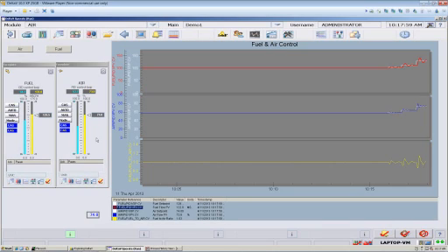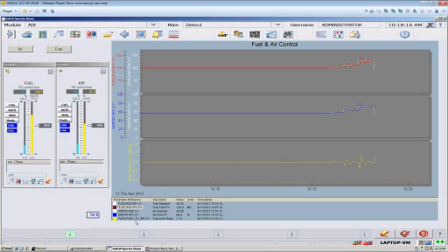And as you can probably predict, if we make an even bigger change yet, our ratio is going to be even worse yet. Step from 74, let's do a 20% change, all the way down to 54. And what we saw is a 50% error, at least a 40% error there in our fuel to air ratio. If this was a real burner in the real world, this might have flamed out and not even been online anymore. So we can do better than this.